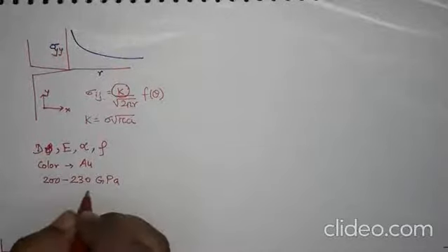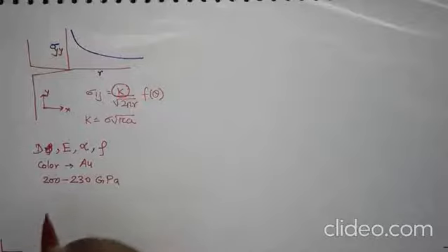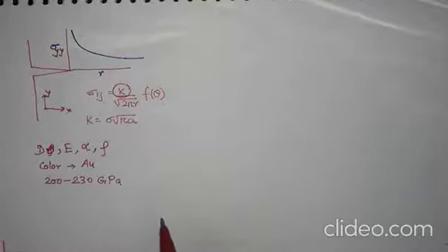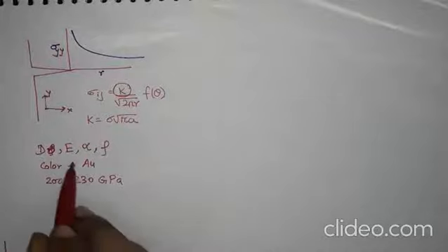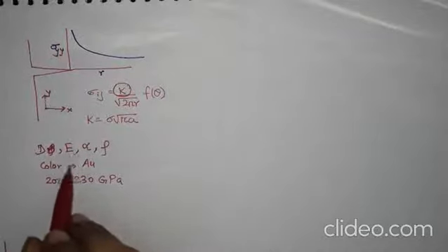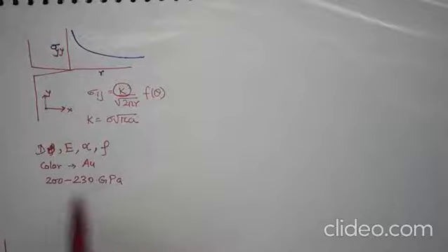They also belong to the same family of steel, but you cannot say that mild steel and Maraging steel are the same thing, because one has a yield strength of approximately 200 megapascal and another one has a yield strength of approximately 1000 megapascal. So these properties can also be very close, but they are the behavior of the material.